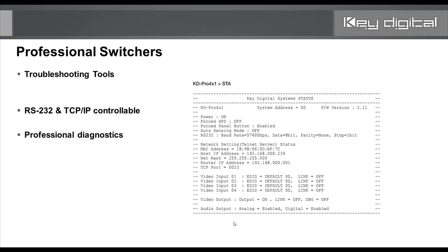So essentially, your TV is on, but you have a failed link. Well, it's got to be the signal's not coming back to the source or to the switcher. So what could you do? You could force hot plug, and we could say, well, it might be voltage related, so let's just force the voltage so that the source is outputting, or the switcher is outputting anyhow. Or you could look at your wiring, you could look at your extenders. You may have a connectivity problem in between the switcher and the monitor.